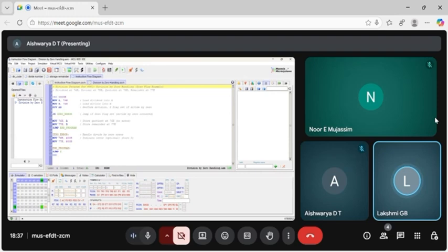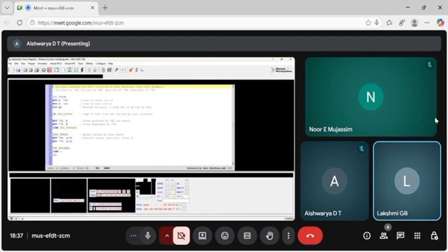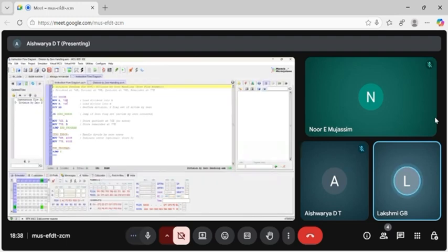Code explanation. Load dividend, MOV A, 74H loads value from memory address 74H, the dividend, into the accumulator A. Load divisor, MOV B, 75H loads value from memory address 75H, the divisor, into register B. Perform division. DIV AB divides A by B.